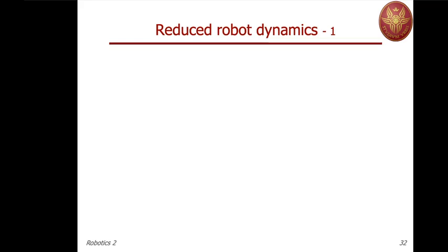Now, at the level of dynamics, this is quite a similar situation. In the first case, your objective is being on the surface, so you're projecting the dynamics in such a way that you always satisfy the constraint. In the second type, when we used the reduced gradient, we decomposed the joint space in two sets of variables, the basic variables and the redundant ones.